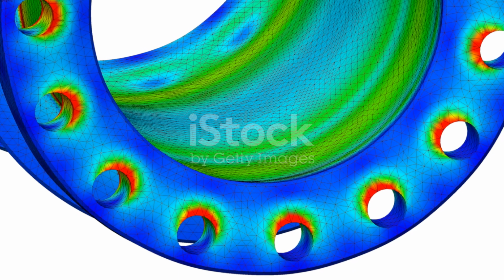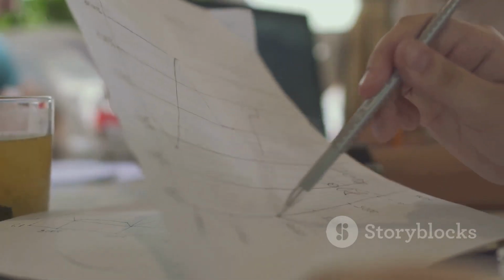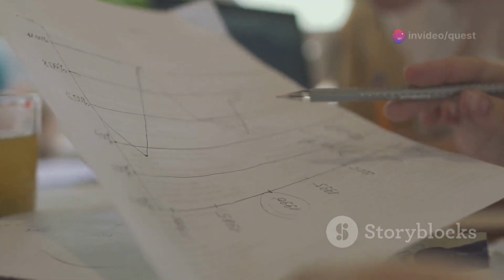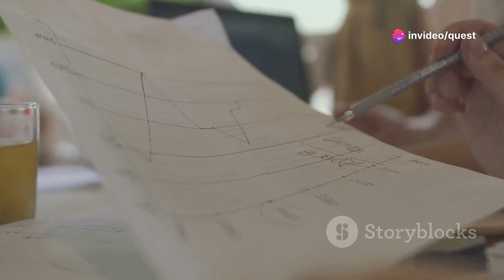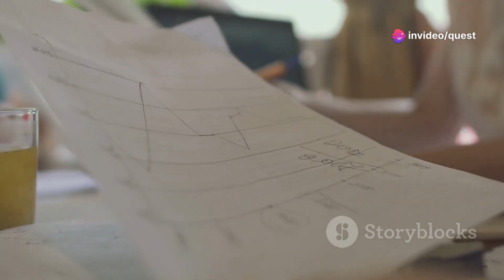The origin of this plane is the average stress. Next, we plot our given stress state on this plane. This point, known as the stress point, represents the normal and shear stresses on a certain plane within the material. Now we're halfway through the construction of Mohr's Circle. The next step involves a bit of geometry. We're going to draw a line from the origin to our stress point.